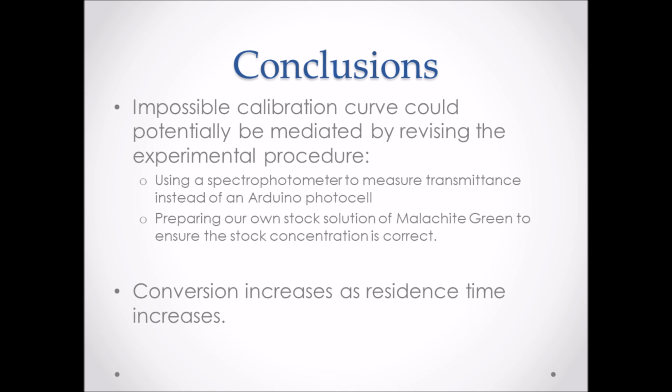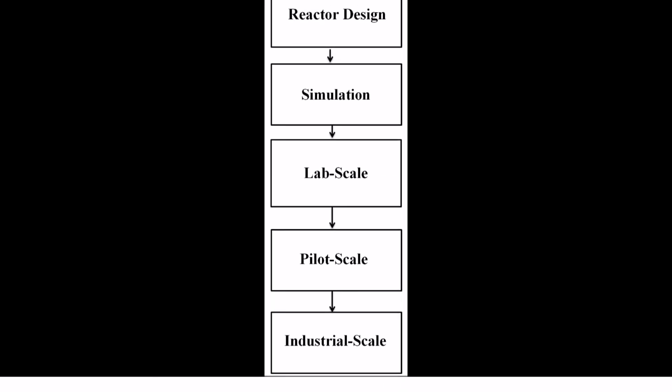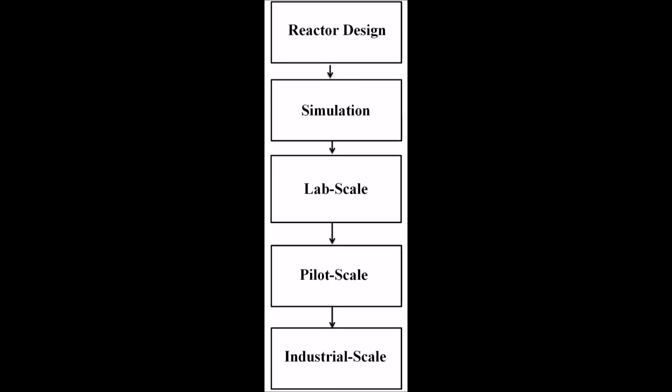We were able to show a few positive results despite the standout calibration problem. We confirmed that conversion increases as residence time increases, and we also demonstrated the principles of lab-scale reactor design. CAD rendering to design the reactor, simulation to predict the reactor performance, 3D printing for reactor construction, and experimental tests to determine reactor performance in practice.